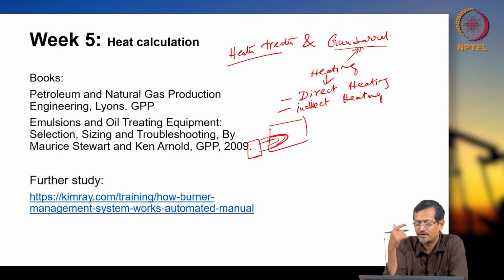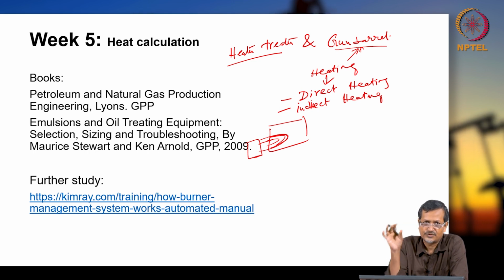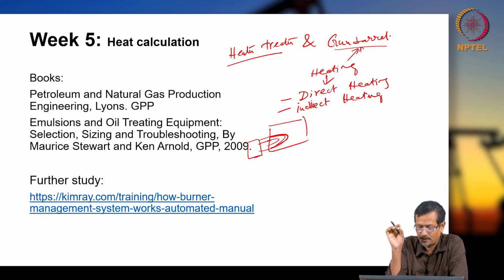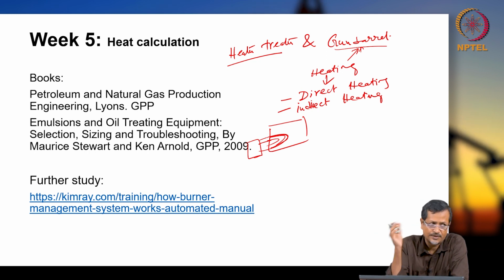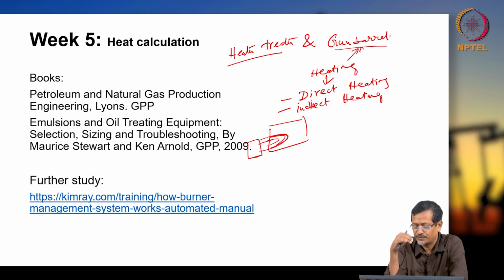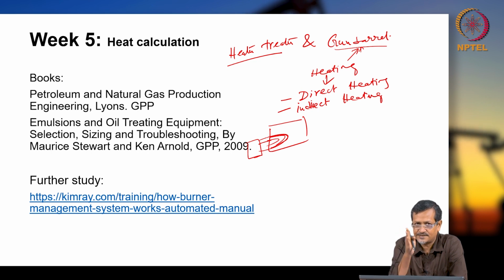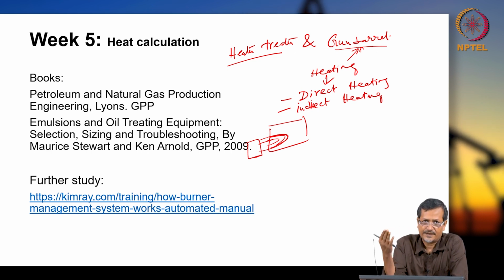But if you are going for direct heating, so in that case temperature can go very high, so in that case accident prone, it is possible some accident also. So in that case you have to fit like water level sensor, you have to put your temperature sensor, you have to put some fire supply cut system, so that system can be made safe.